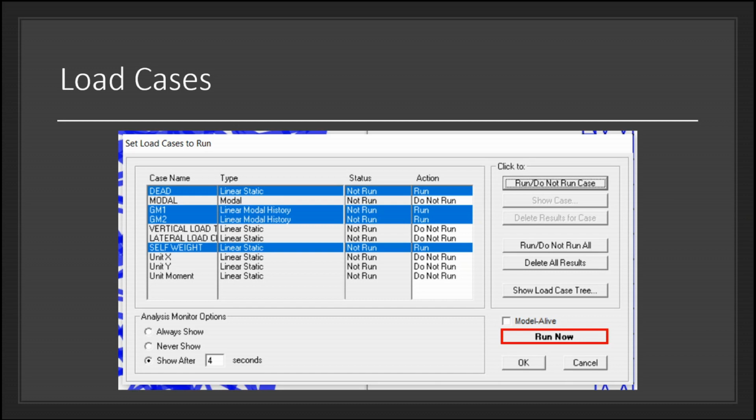So this includes the metal rods and the plates you may have seen in the pictures of the previous competition towers, as well as we can put in ground motion 1 and ground motion 2. And our last load case that we will run is the self-weight load case. And this is a load case that does not include the metal rods and plates, just the tower itself.